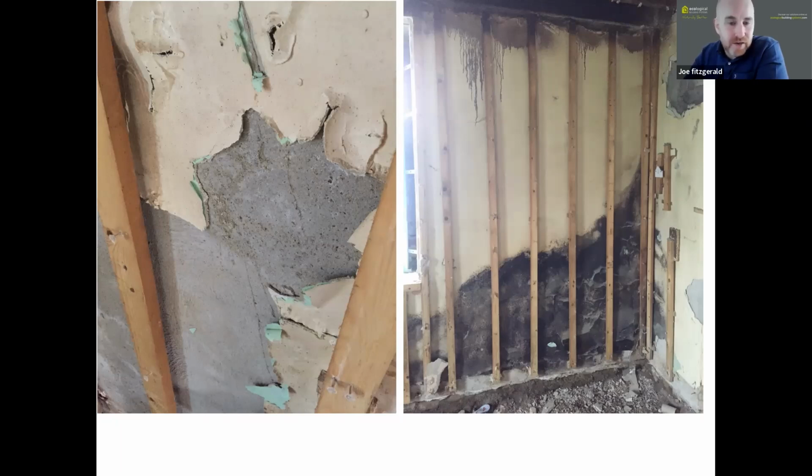So he was really cultivating bacteria in this instance. And you can see the way the gypsum has all completely pulverized and fallen from the substrate, because gypsum has no ability to buffer moisture at all. And because it's also pH neutral, mold will get a hold on it really, really quickly. So I use this slide to demonstrate that gypsum is not a great background to insulate across.